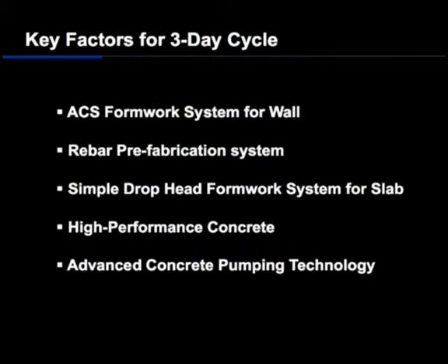So to maintain this 3-day cycle, we decided to use the automatic climbing form system for the walls, and also a rebar prefabrication system, and a simple drop head formwork system for the slab, and high performance concrete for early stripping, and advanced concrete pumping technologies.